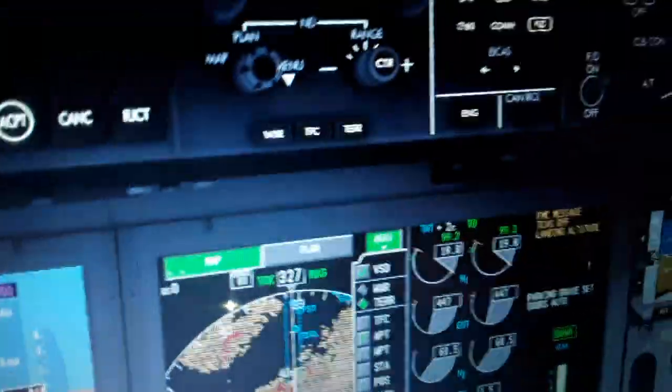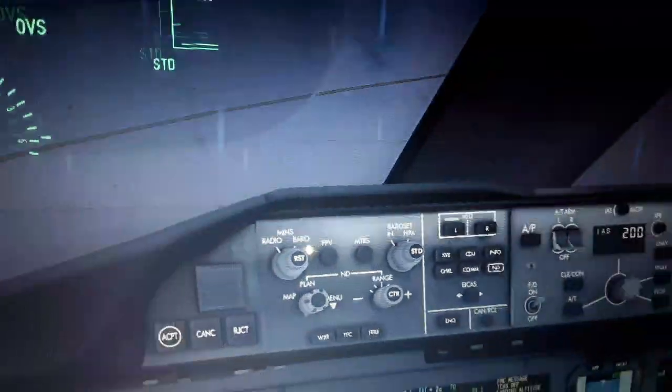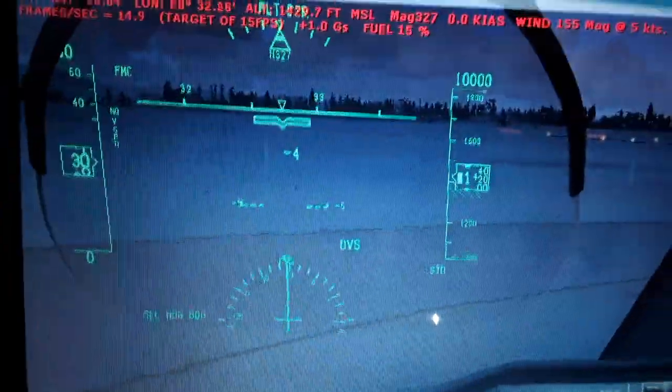So we have set the barometric altitude over here to 29.92 inches of mercury, or 1013 hectopascals. Right now we can set it differently. You will see all displays the same. So you see this barometric altitude right now at 29.92 inches of mercury.